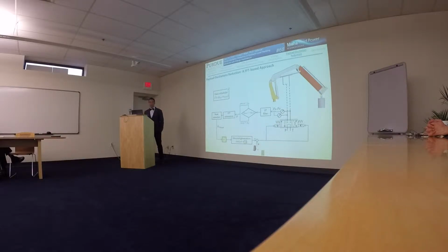To do that, we use the same optimization process and again the same gain scheduler approach, except that now the gain scheduler is indexed by the operator command, and also by the oscillation frequency of the payload and the low-pass filter pressure. The output of this gain scheduler indexes these two parameters.